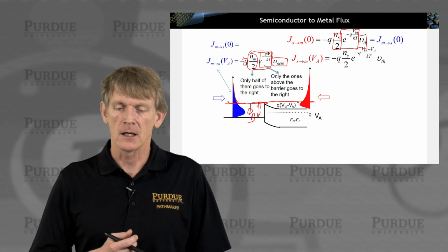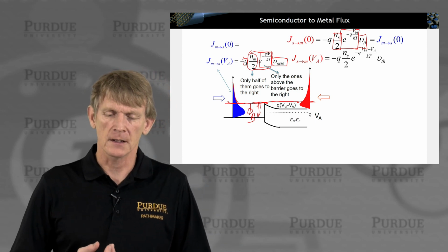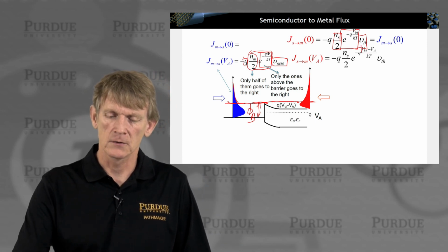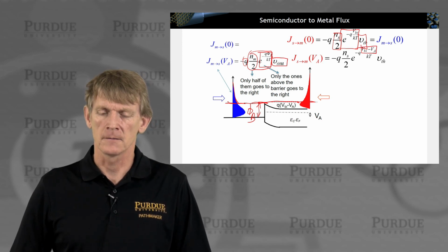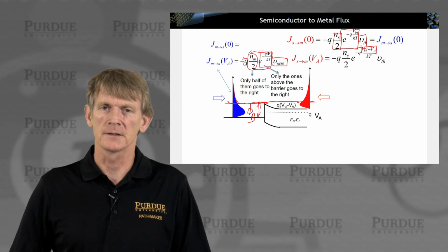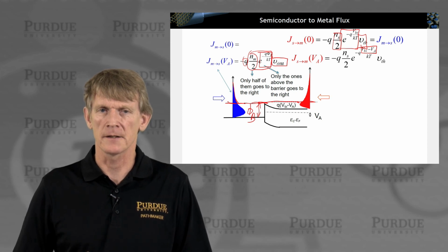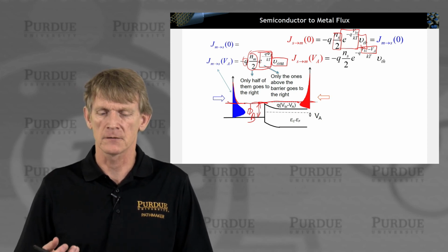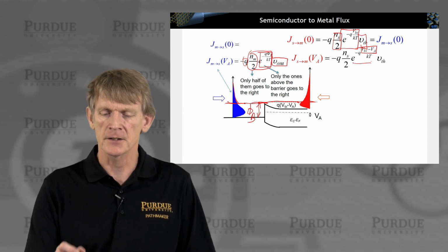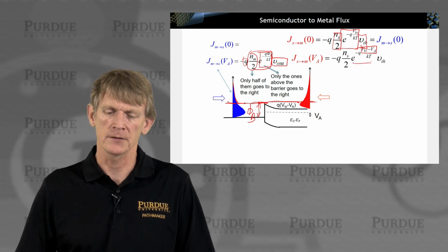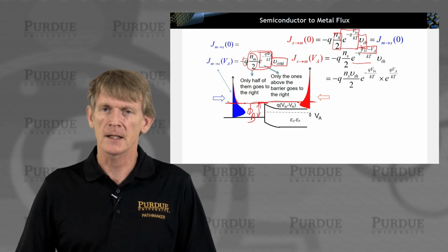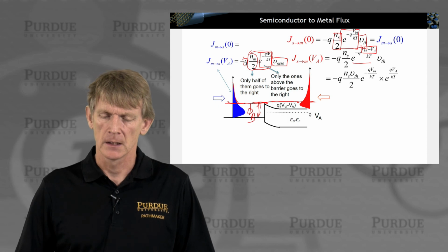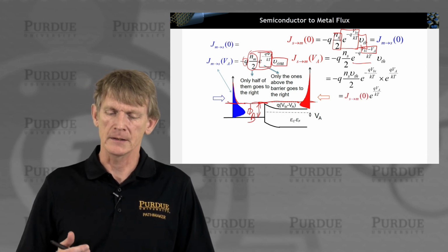Okay. Now, if I apply a voltage on the semiconductor side, all I do is substitute in addition the bias into the built-in potential. So I lower the barrier and therefore increase the number of carriers that can flow. That sits in an exponential, and that gets me the exponential increase of carriers that can flow across the junction. All right, I'll split that exponential into just two terms as a product, and I identify, oh, look at this.